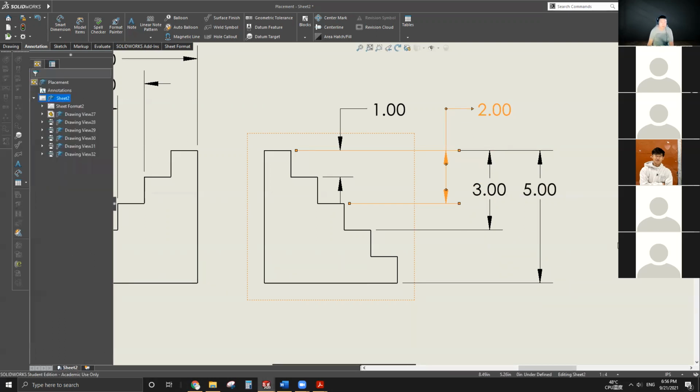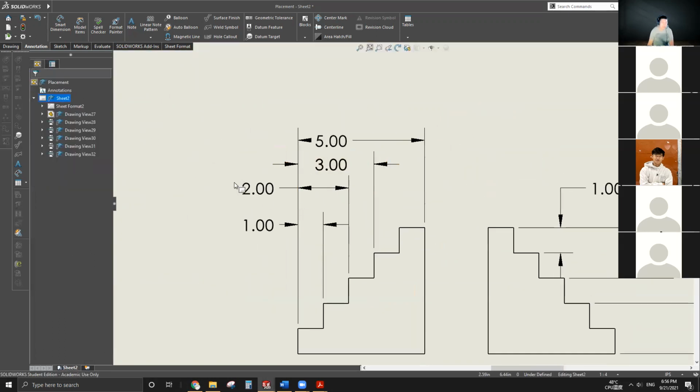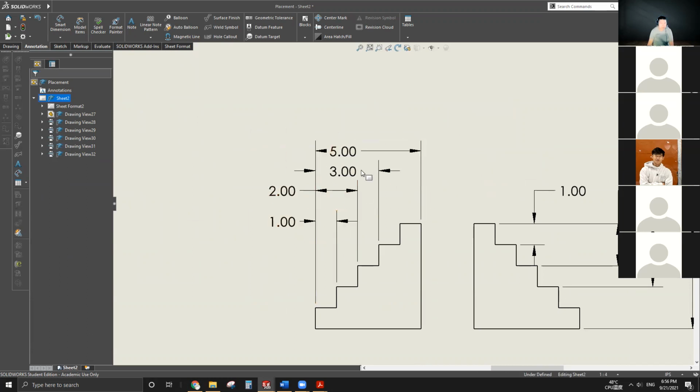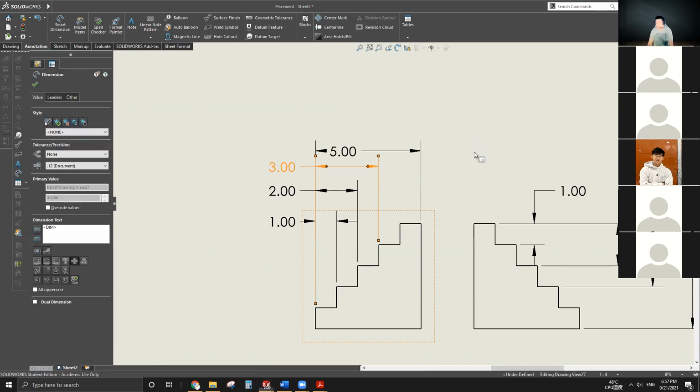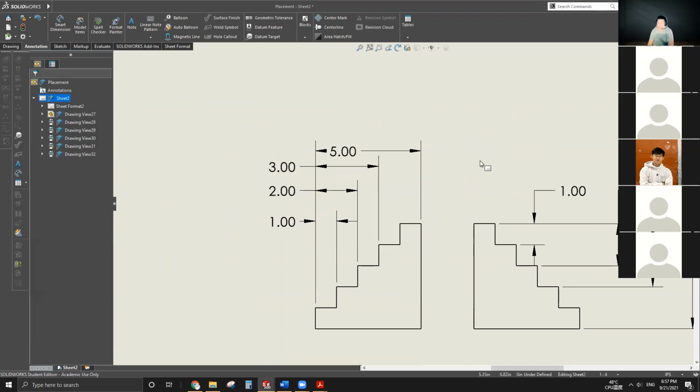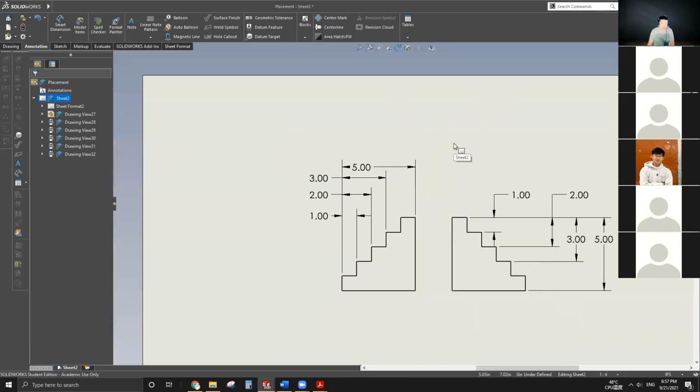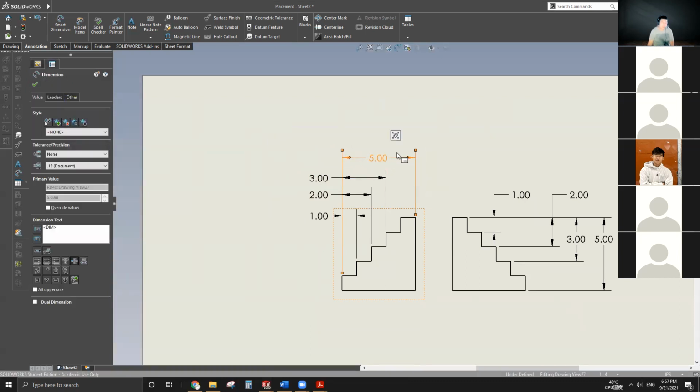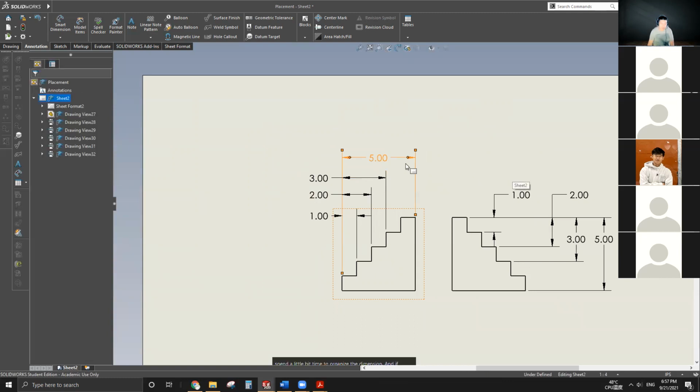This is just a little bit of formatting to show you. When you have a very crowded drawing, you can manage it like this or like that. If you place it like that, it's going to be a cross, and if you place it like this, it will be a little neater. You know what I'm talking about, right? After you annotate your drawing, spend a little bit of time to organize the dimensions, and if they can be in the center, please place them in the center.